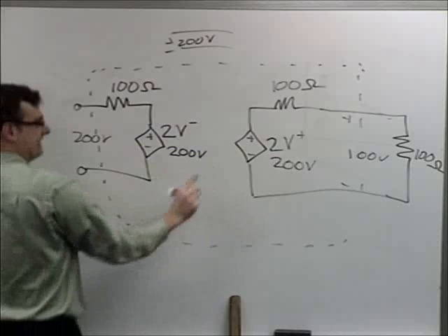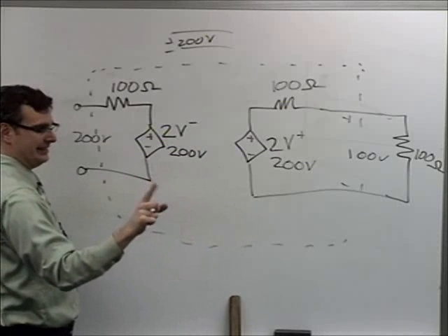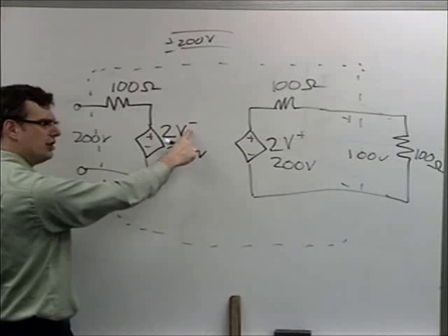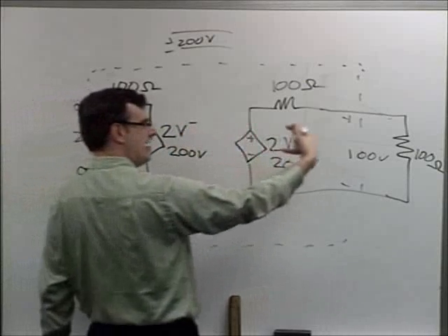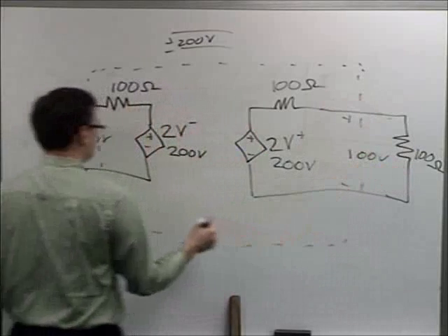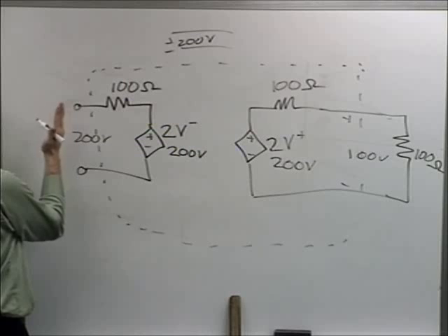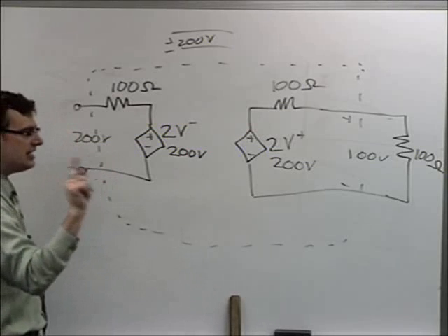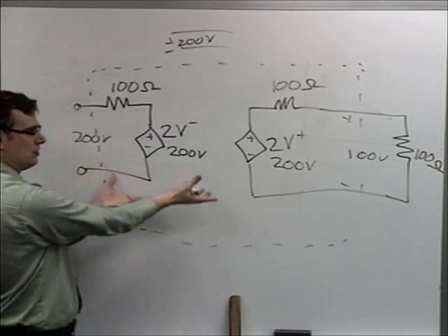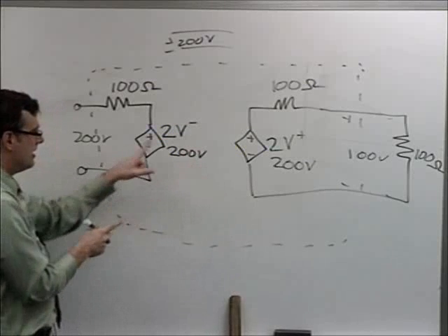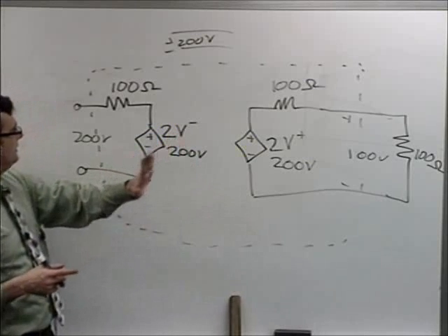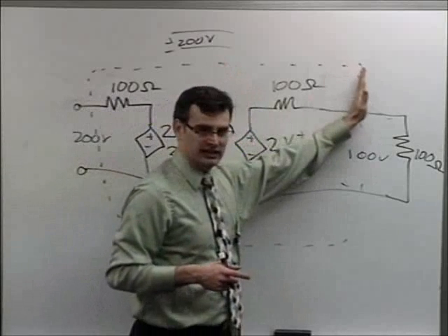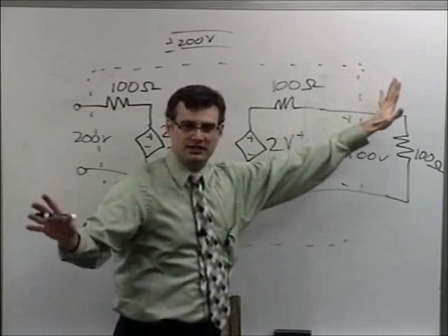Now, immediately as the finger touches, and that's the key word, immediately, it means that just a tiny, tiny fraction of a femtosecond after I make the change, this V minus isn't going to change either. Because this V minus waveform got put on the line at least one transit time ago. And so I can still use this to model the other end of my transmission line until at least one transit time elapsed. And so that's always the key point. This is one thing that confuses students when they start putting this circuit model into their analysis of transmission lines. This V minus is the V minus observed at the end of the line. This V plus is the V plus observed at this end of the line. And never the two shall mix.